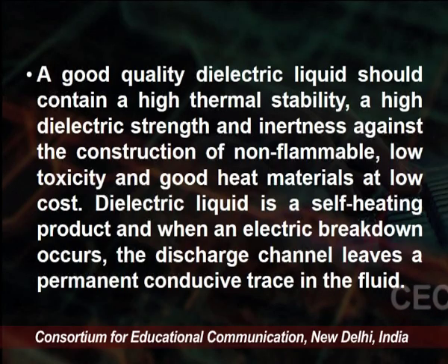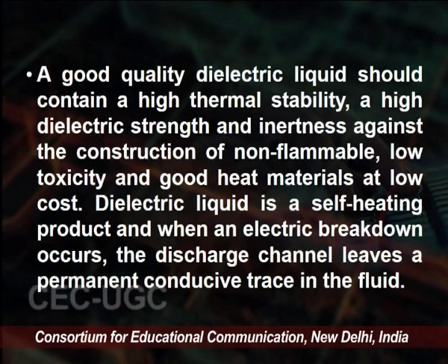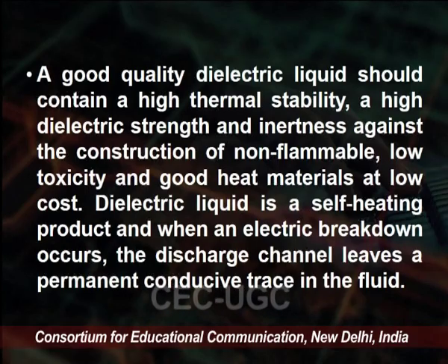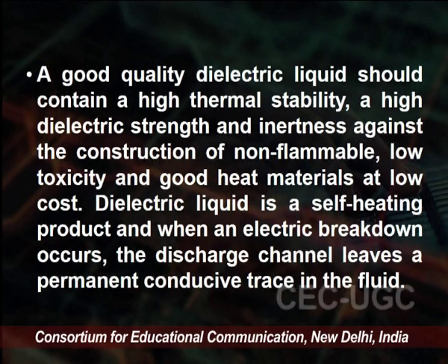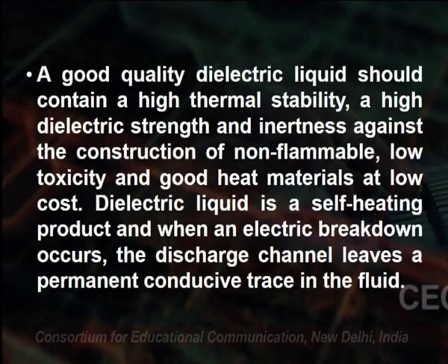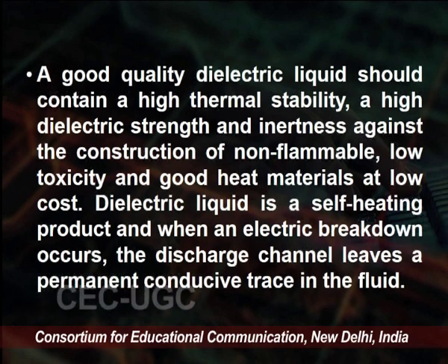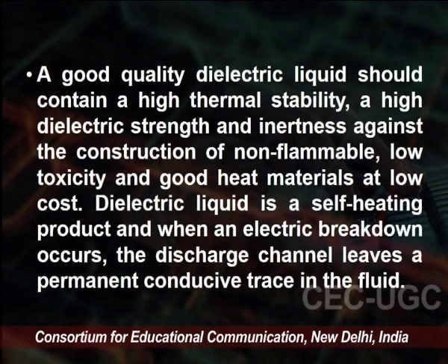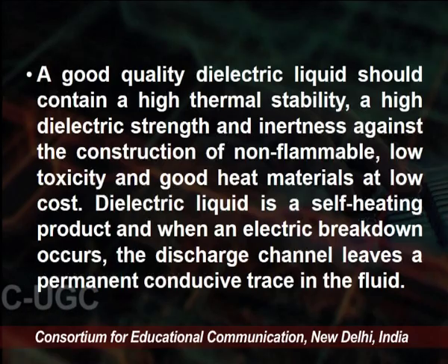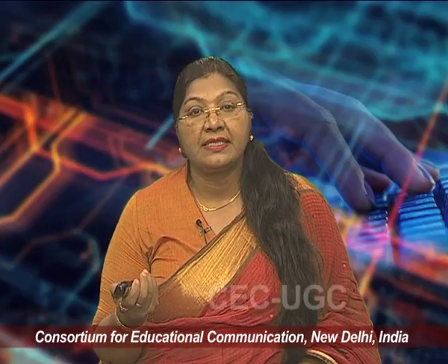First, it should have high thermal stability, a high dielectric strength and inertness, and it should be non-flammable. It should not be flammable. They must have low toxicity and good heat transfer properties at a low cost.